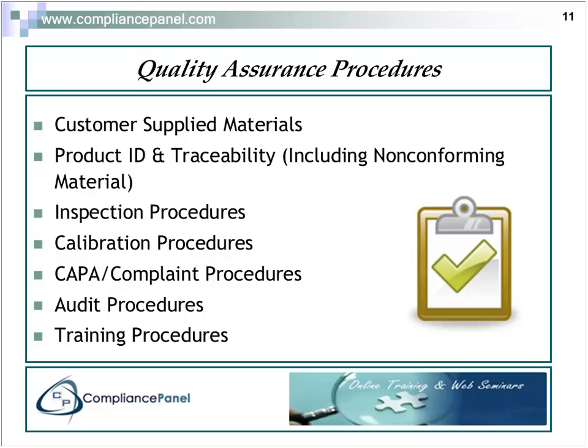How do I know this sample still works? In some cases the golden sample may not be one that passes everything. It may have deliberate failure modes included, so that you can show that when everything passes, it passes, but also when there are failures involved.